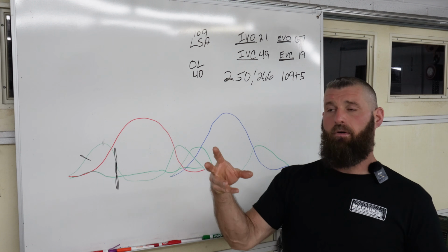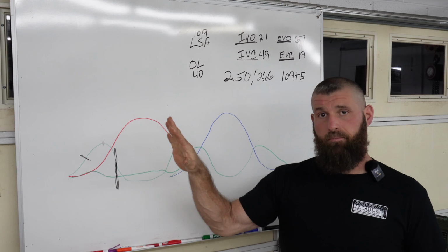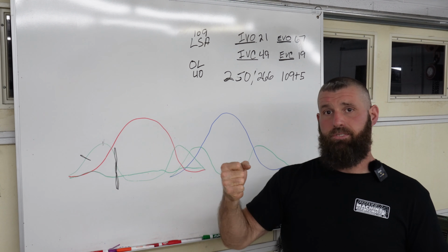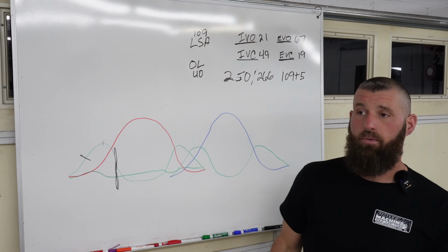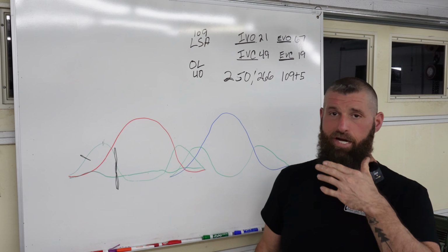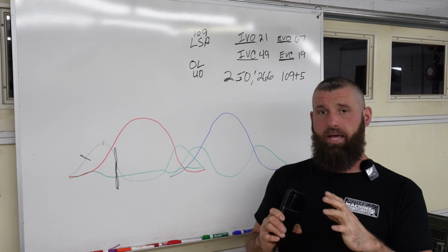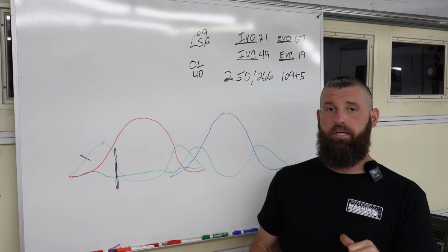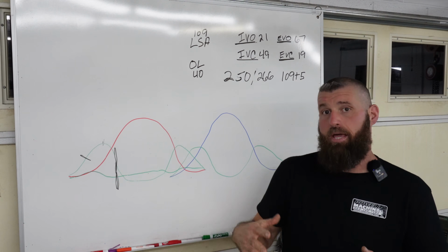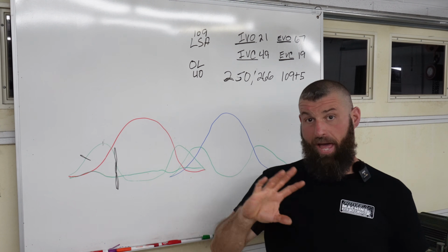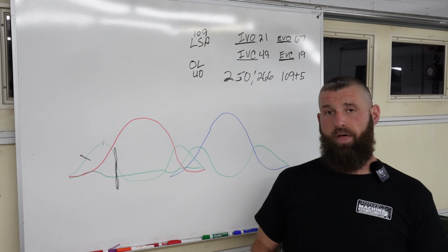So that's another consideration. In the street stuff ain't so bad, hydraulic, low pressure, but when you get into race stuff, some applications you just can't get enough push rod in the motor. It won't fit through the head. So in those applications, you have to be really aware, a softer lobe and a smaller spring package with titanium everything may be more ideal because of system flex, and you just can't help it. So you just need to be aware of that kind of stuff too, because that is a big deal when you get into that world.